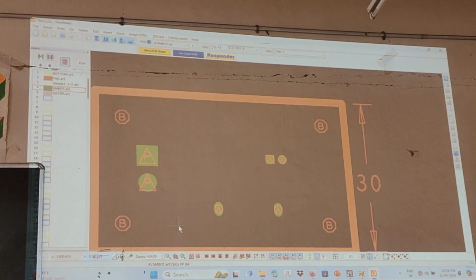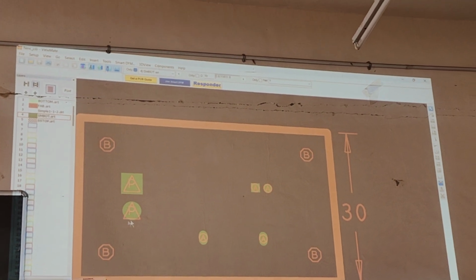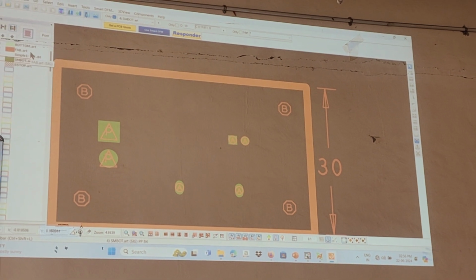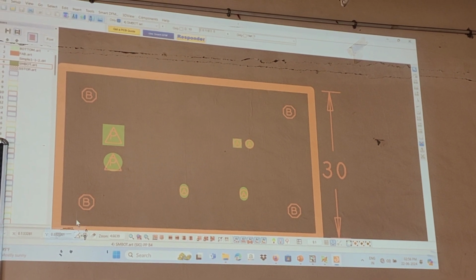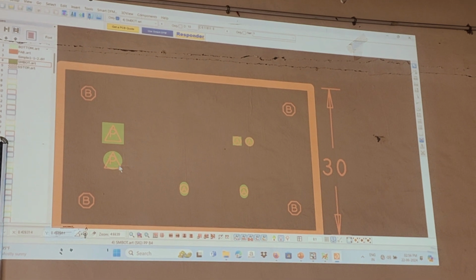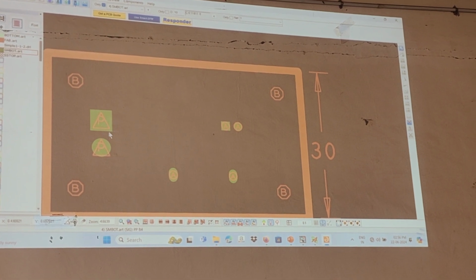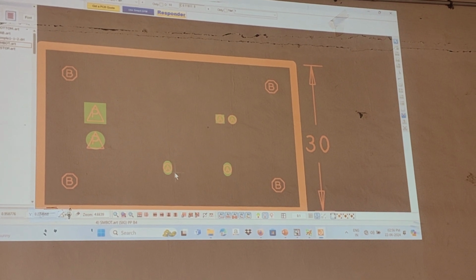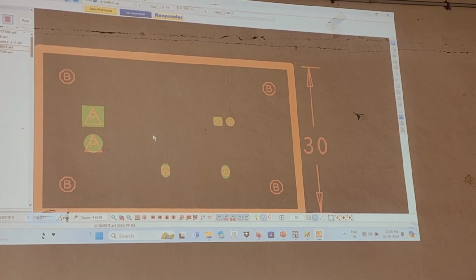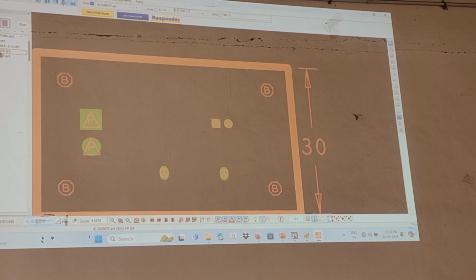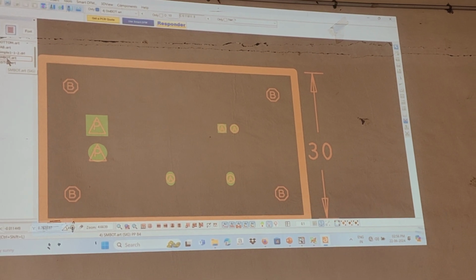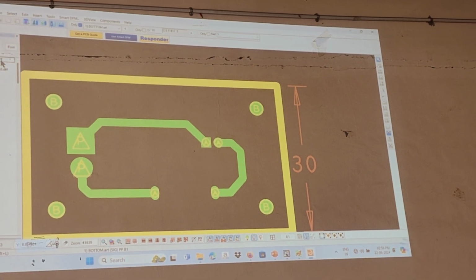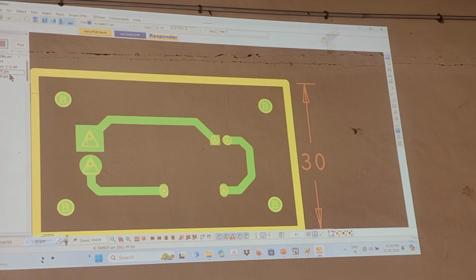Here we have to re-verify when we are having the SM. This is SM bottom and fab layer selected. So fab layer will have the drill information and SM bottom will have the pins alone. So if these two are merged and there is no extra drill outside, then no need to worry, we can proceed. The same way for the bottom layers also, we can verify. These are all verification procedures.